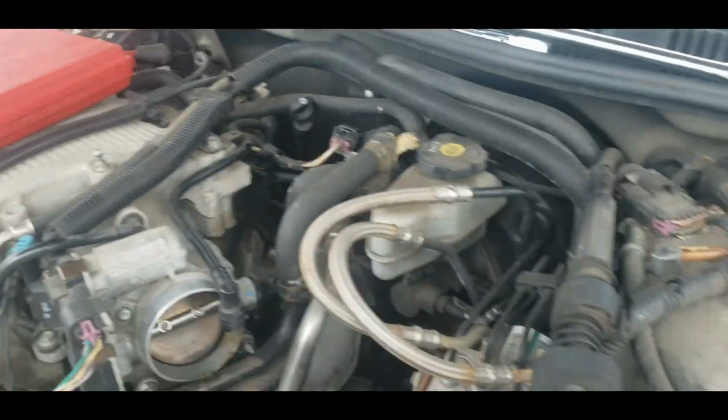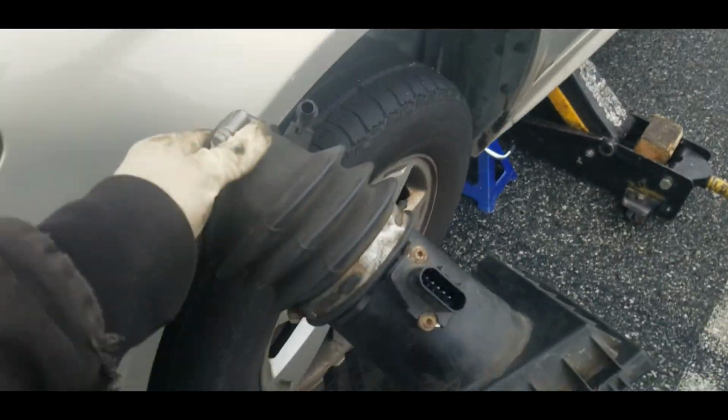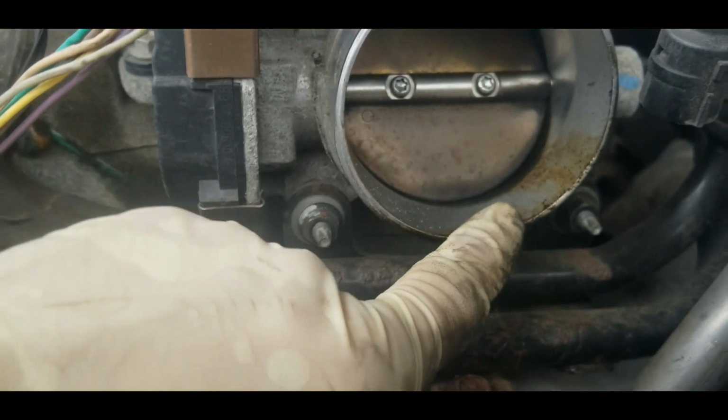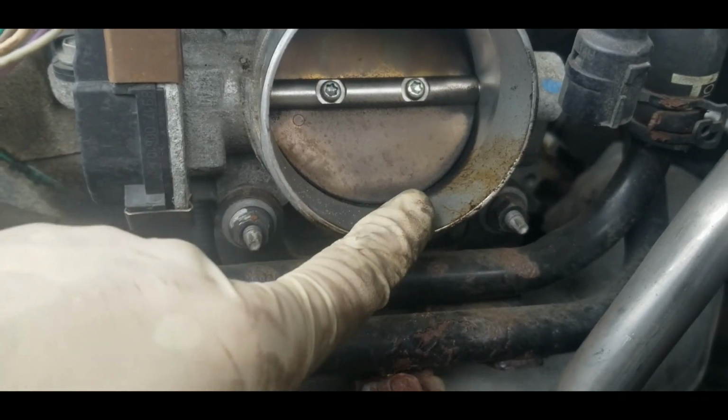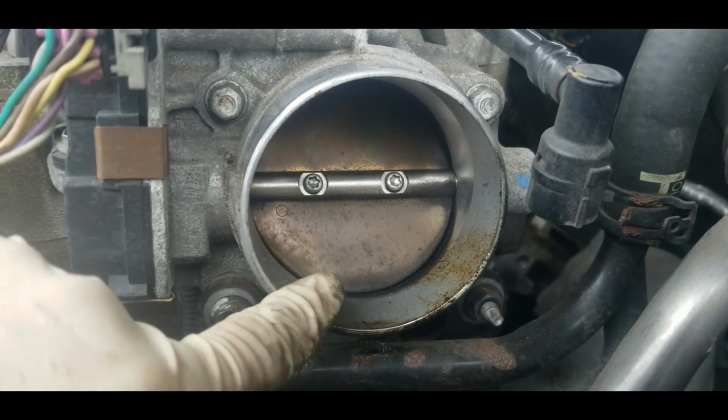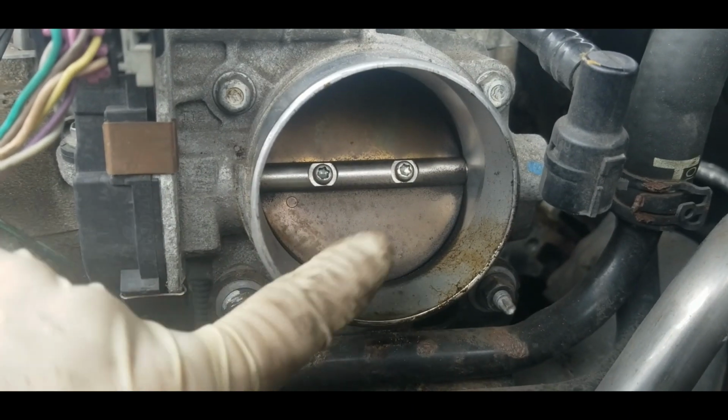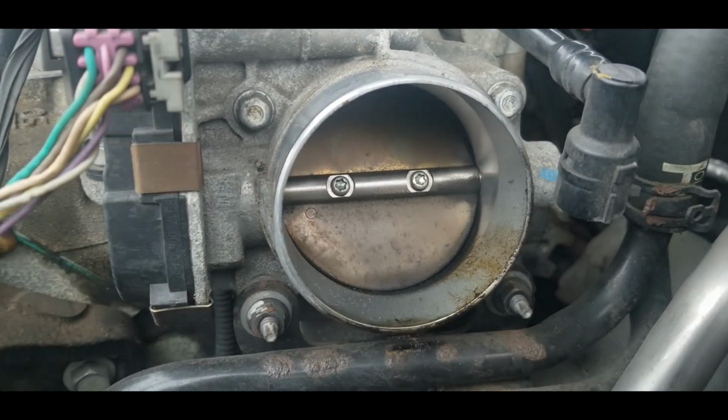So as you can see, I had to take this air sleeve, part of the air box, off to give me more access. By the way, take a look at the throttle body, and you see how dirty it is. That is not good. It should be serviced. It should be cleaned up. That can give you a bad idle. It could give you